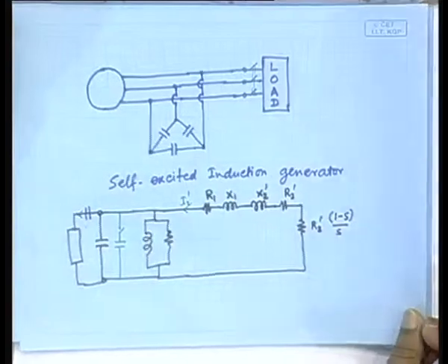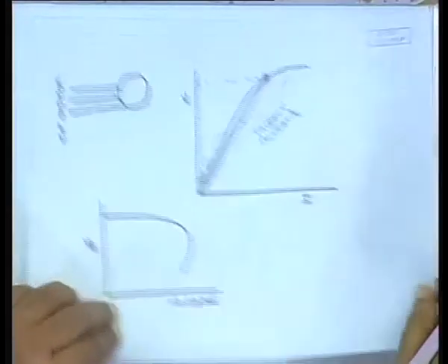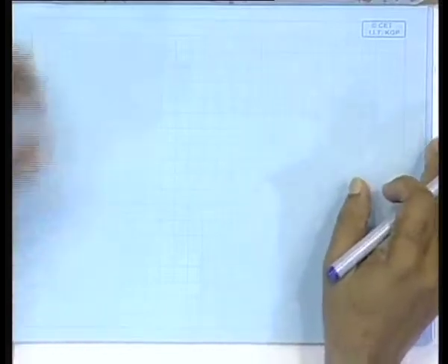Okay. So, we have learned, to briefly recapitulate, the main advantage of connecting an induction machine instead of a synchronous machine was that the induction machine is able to operate at variable speed while maintaining the constant frequency. That was the main one. And the second advantage is that the induction machine is cheaper, far cheaper than the synchronous machine. It is rugged, it is very strong. So, its durability is higher, but the disadvantage is,